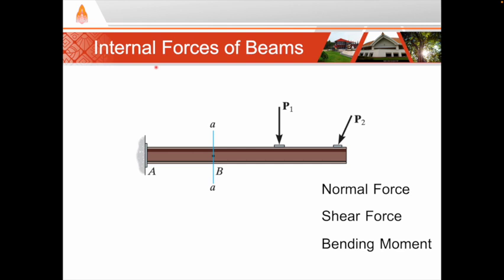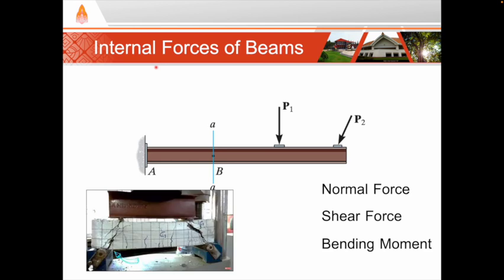Together, we can call these three forces the internal loadings. These internal loading forces are important to designing a structural component. For example, a material like concrete will have a shear strength. In other words, if the shear force is greater than the shear strength of the material, the beam will fail.